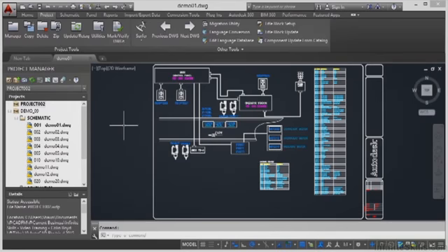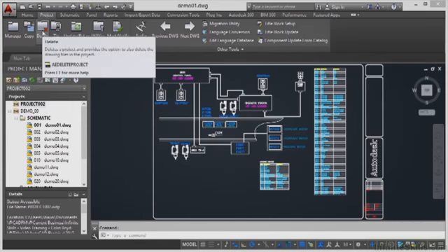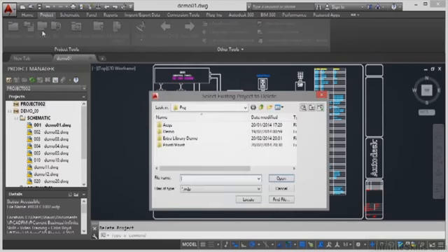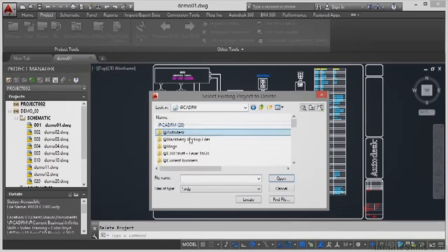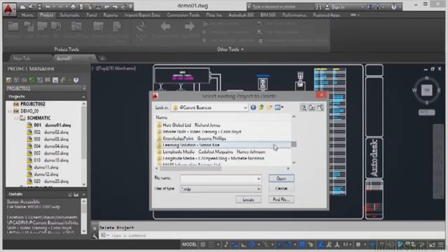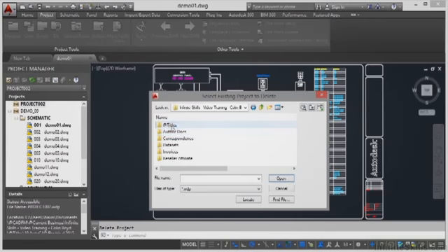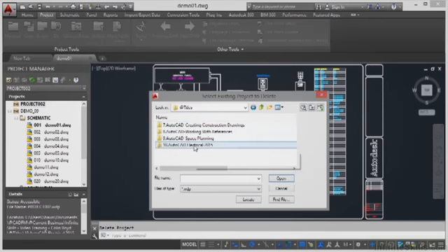The trick is to use the delete tool in the project tab on the ribbon in AutoCAD Electrical. There's delete there, so I click on delete like so. That'll bring up select existing project to delete. So what I've got to do now is go and find it. That's going to be in my libraries, CAD FM, current business here. I go and find Infinite Skills, scroll down the list. There we go. Into titles, and there's my AutoCAD Electrical 2015.